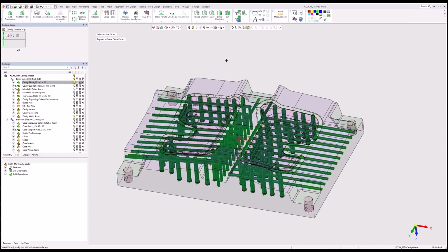I'm going to select my water components. Middle button. Now it wants me to pick the active faces. These are the part faces. So in this case, it understands those are from the cut active. Again, you can select it by color if you had an imported job from someone, maybe through STEP, as long as you can isolate the part color or part faces, you can still run this without any issue. I'm going to say OK to that.